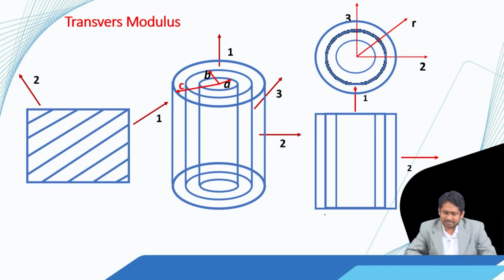Now, to find out the transverse modulus, we cannot directly apply this two cylindrical model. By the way, in the theory of elasticity based model, we always have concentric cylinders, so this is called a concentric cylinder based approach also. In the previous cases, we had always two cylinders, the inner one with fiber and the outer one with the matrix properties, but that only gives us bounds for the transverse modulus.